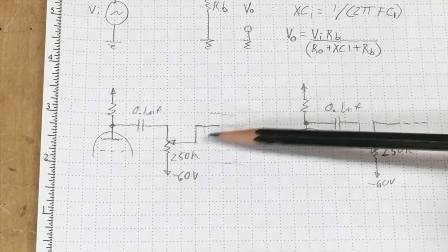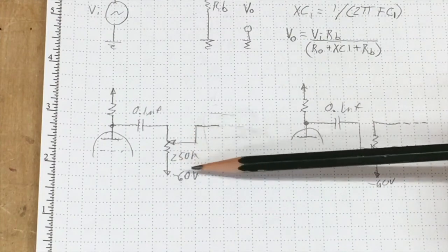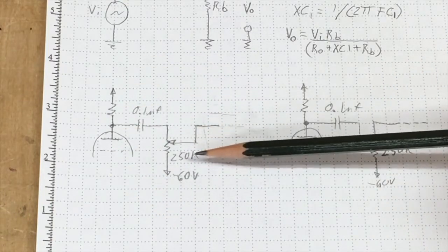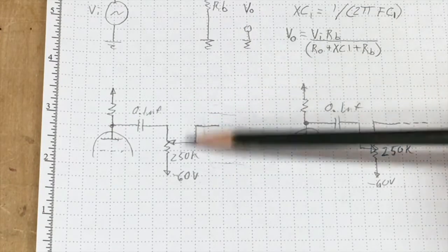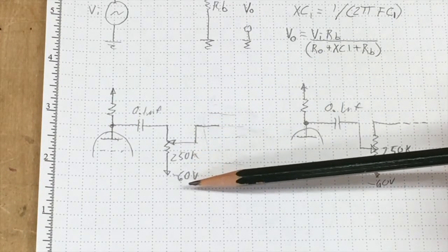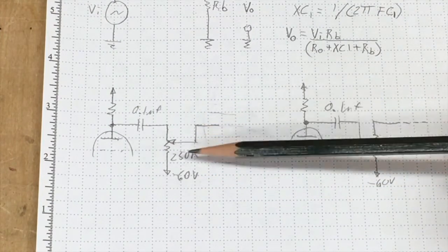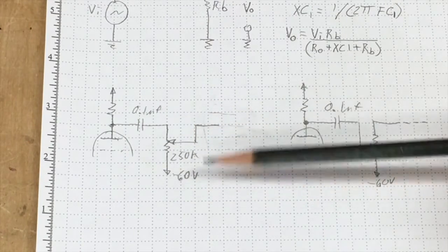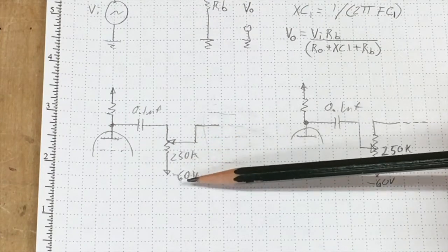The other thing I don't like about it is when you change this value, you change the actual output resistance of this entire circuit, which will change the tone of the circuit as you adjust it. Third thing that I don't like about it is you've got minus 60 volts on one leg of a potentiometer that's on the front panel of your device. The front panel that gets moved from car to car, walks through doorways, could get whacked by anything, could be damaged, and then a musician's hand is going to touch it.